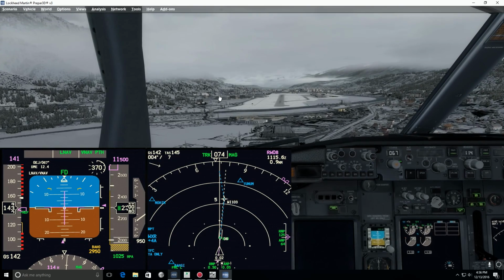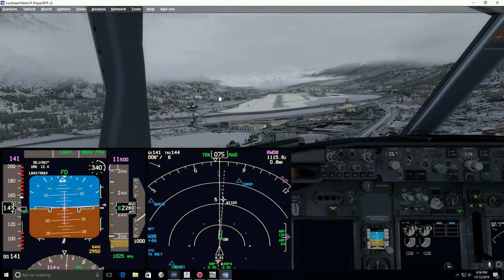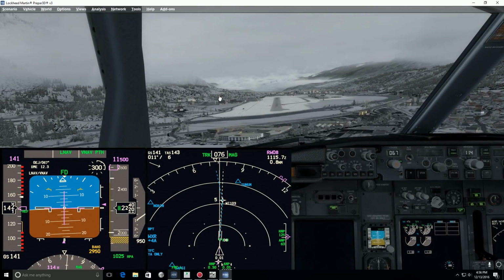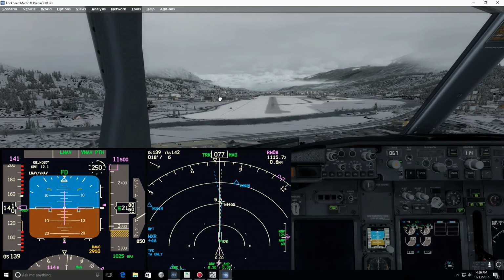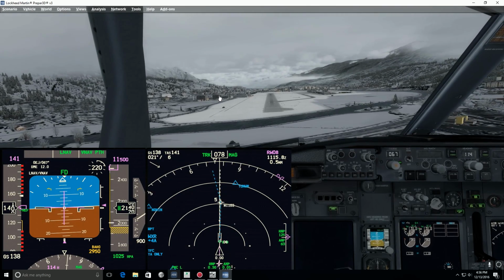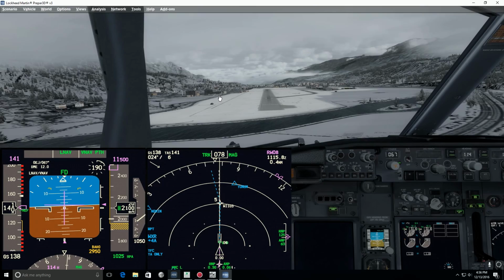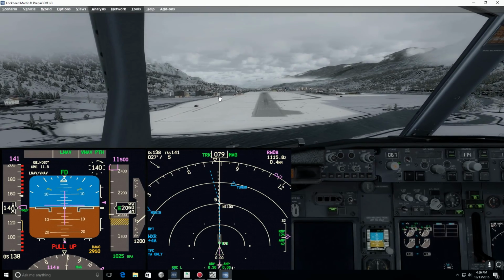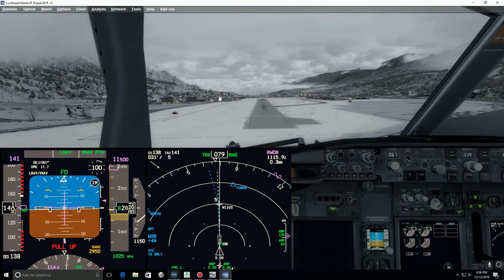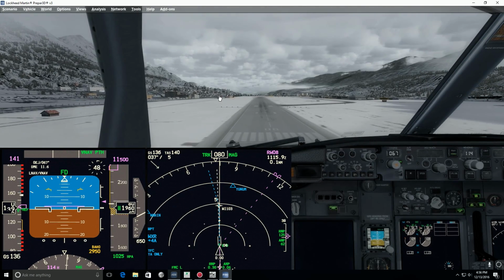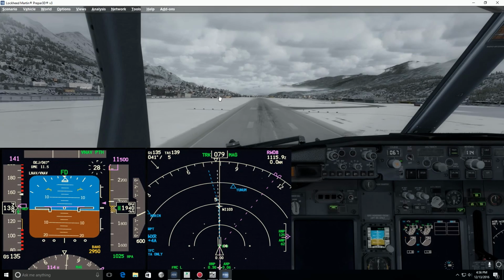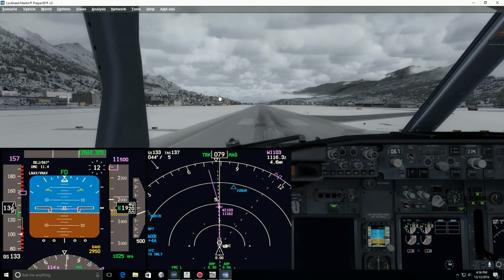And 500 stabilized. Now the PAPI is coming in view. Speed is good. 300. See, the flight director is still showing good, so we can follow it. Sink rate. Sink rate, sorry about that. Coming down. 50. 30. 20. 10.